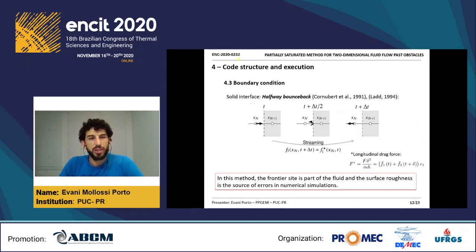For the boundary condition on the solid interface, I'm using the halfway bounce-back, which considers the streaming step at half of the distance between the fluid sites and solid sites. So the populations are turned back to the opposite direction at time t plus delta t by 2. So at time t plus delta t, the distributions are in the opposite direction.